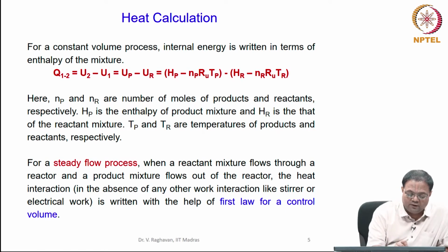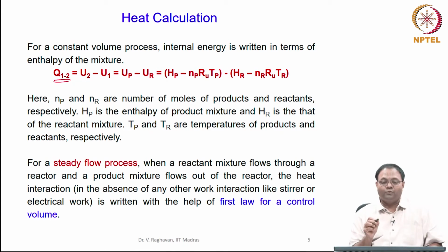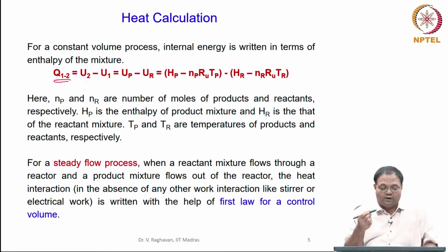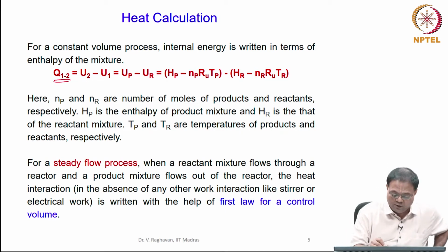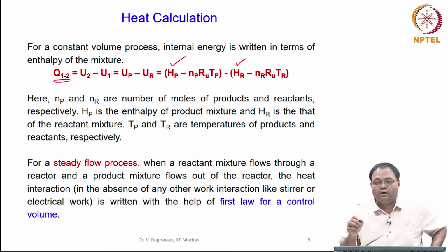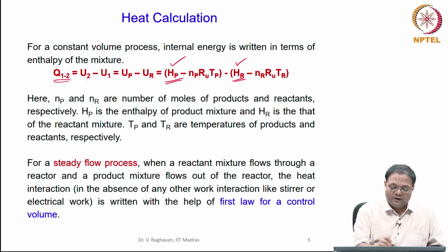We have arrived that the heat interaction will be equal to U2 minus U1, or Up minus Ur. Generally, it is not easy to measure internal energies. It is easy to measure the enthalpy of individual species, and so it is easy to calculate the enthalpy of the product mixture or reactant mixture. Normally they are tabulated, say, on the NIST website. The enthalpy tables are available, but internal energies are calculated based upon the definition of enthalpy.